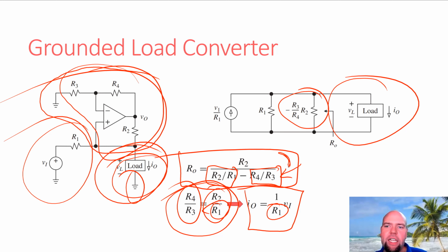Even being a little bit off matters, because op amps are generally very good at producing close to ideal outputs. The non-ideal effects, we can always improve by a factor of 1 plus the loop gain, or 1 plus the return ratio. And if you're improving something by a factor of 1 million, that's fantastic. But you're never going to be able to buy resistors with an accuracy of 1 millionth, or maybe you could. You're going to be spending a lot for that.